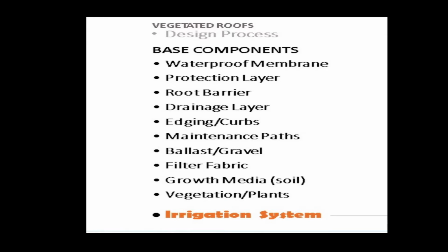And a lot of times what you're doing is not necessarily working through the details to figure out the best solution. You can also look at it and say, well, if we raise the parapet a little bit, we could actually remove edging and run the soil and the plants right up to the edge of the roof, which adds more vegetation and less cost to the project. So some of the work through that is actually reducing cost and finding the optimized solution.